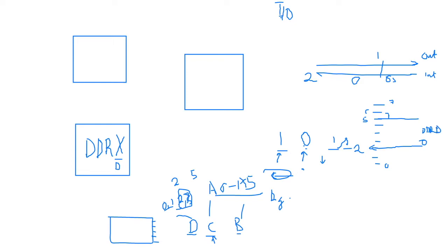Now pin 5 is an output because it's an LED, a light emitting diode. That's pin 5. So we will send a 1 to it. So we want pin 5 to be somewhere here. In the data direction register D, DDRD, we really want a binary where it doesn't matter what the rest are, as long as pin 5 and pin 2 are concerned. We will put a 0 on pin 2 and a 1 on pin 5. By default, the rest are all 0 anyway, because by default they are set as input. And we had a look at the data sheet to see how they are.